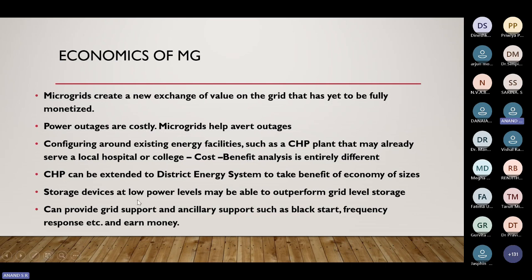So the CHP concept, combined heat and power concept, can be further extended if you go for a comparatively larger area, for a district, or for a part of the district, including a city area. It may not be workable in a purely village area because your daytime demand may not be matching, but in the suburbs and in the proper city, it can be implemented. Then storage devices at lower power level are comparatively cheaper as per the experience that we have, because as the capacity increases, the cost of storage increases exponentially.